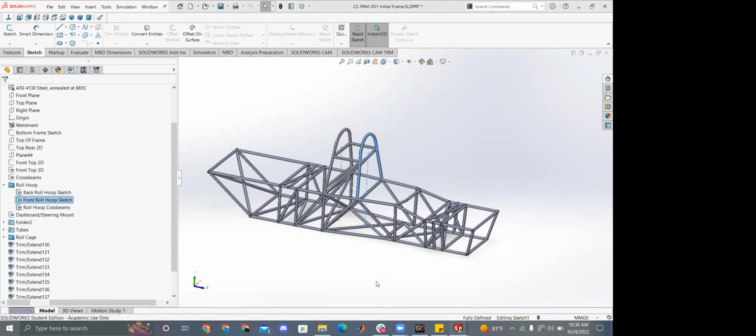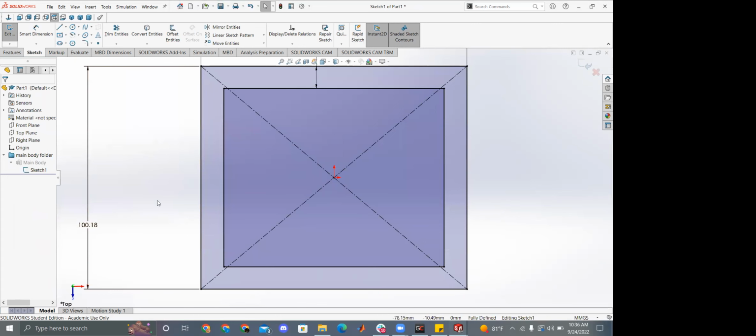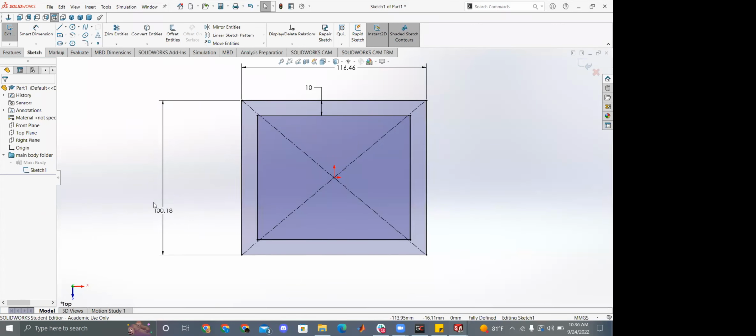So with that, let's keep on going on. Fillets. Now, fillets are something we talked about a little bit last week. Basically, the motivation behind a fillet is if you have a corner, it creates a stress concentration, and you'll get into it a lot more during your materials class. But the gist of it is, stress is force over area. It's a pressure.